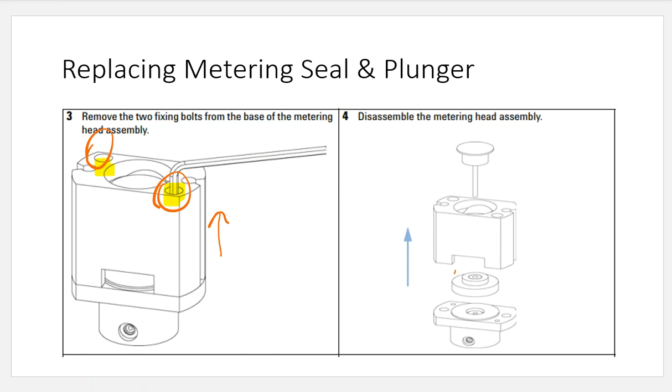I see this kind of guard that's going to be located. I saw that in the pump, and I saw a piston that's also going to be in there. I saw that from the pump as well. So I'm going to inspect those. I'm going to make sure that those look good before I do anything else. Look for damage. Look for wear and tear. Look for dry rot. Make sure that everything looks okay and decent.